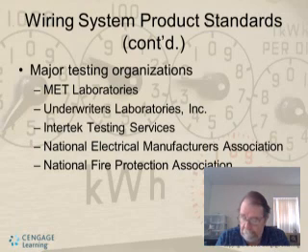And again, the local ordinances: the importance of local, city, state, etc. electric codes cannot be overemphasized. Local agencies can adopt the NEC exactly as written, or can amend the code by incorporating more or less stringent regulations. I covered that a little bit ago, but I want to emphasize that because when you're doing work, you may have to deal with city inspectors, and they may have different code information than what you have.